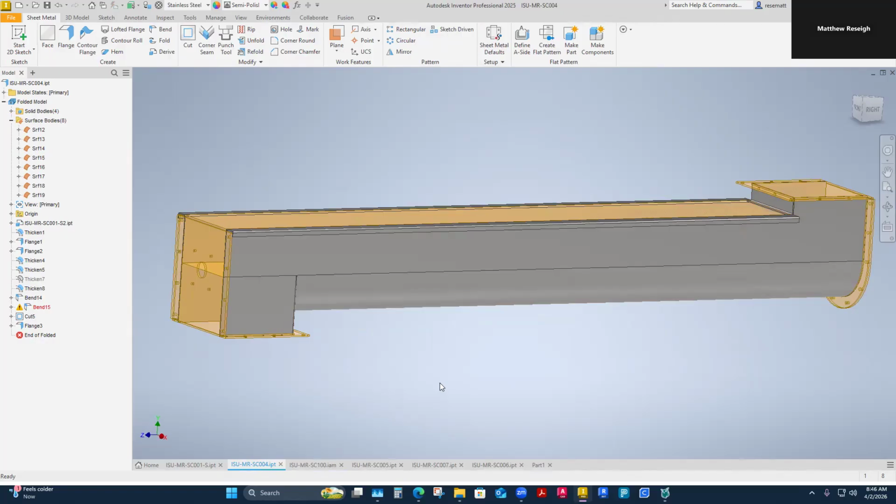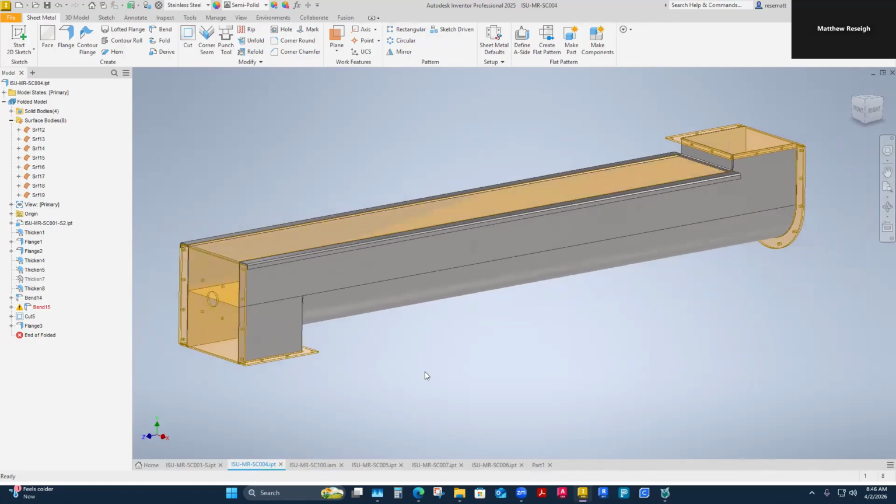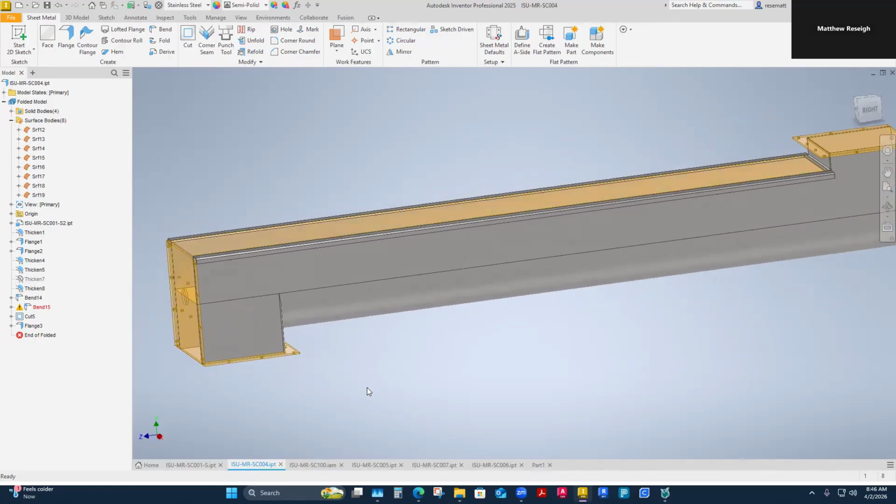So you've got to go back to the drawing board a little bit and say, I'm going to go back to here and make some modifications, and those will feed the assemblies and parts downstream from it. I don't know where the book is where you learn this stuff, but eventually you learn this with some experience. In how to make parts, what we're trying to do is make things adapt themselves, to do minimal work and let that change affect your parts downstream rather than going into each individual part and having to make changes.